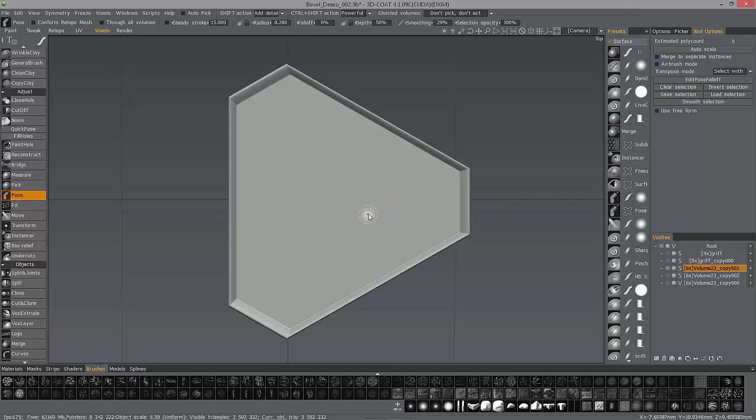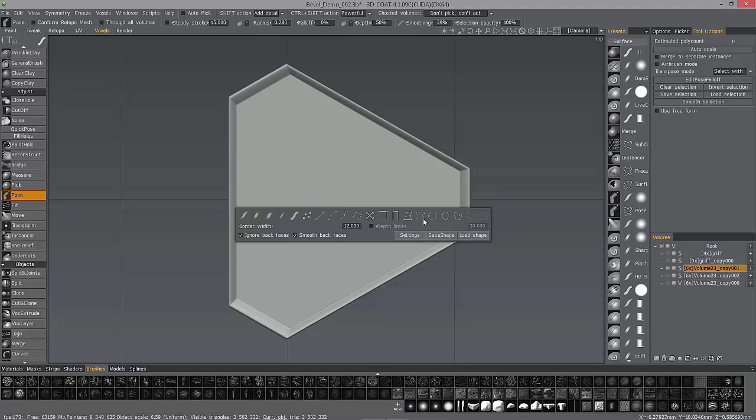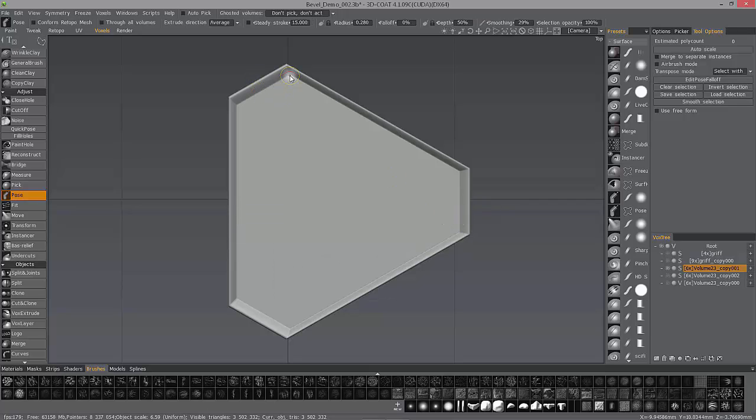And in the E panel, I can hit the E key to bring it right to my cursor instead of having to reach to the left side of the interface each time. And choose a closed spline draw mode. And I could change the point type as I'm actually creating these. So for example, I could right click and harden that edge as I'm working.